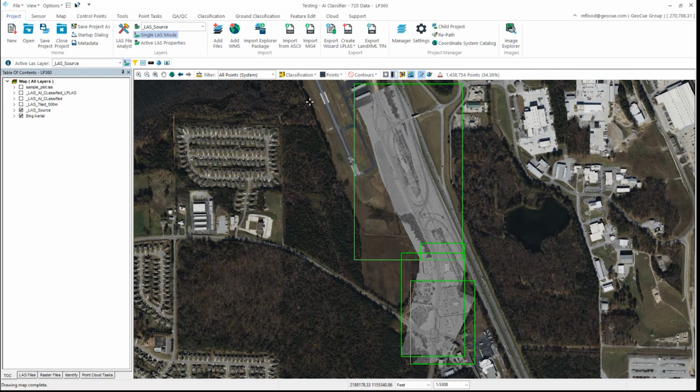That's one of the nice advantages of the AI classifier. You can work immediately from having your geocoded data. You don't need to have seed points. You don't need to generate a seed layer. You don't need several of the prep steps that you need when you're using the legacy adaptive TIN approach. You can just work directly from the data coming out of your geocoding.